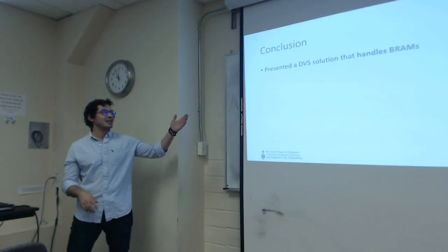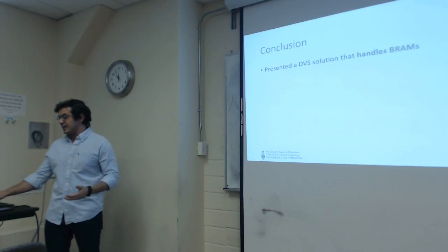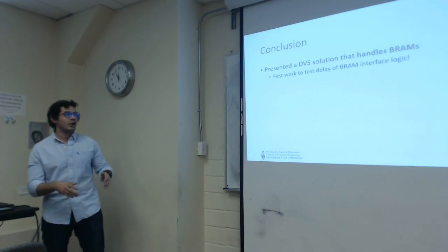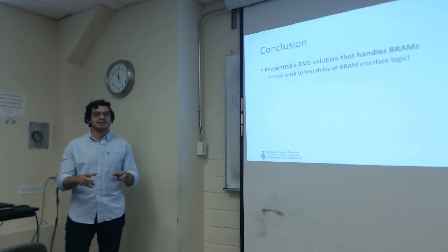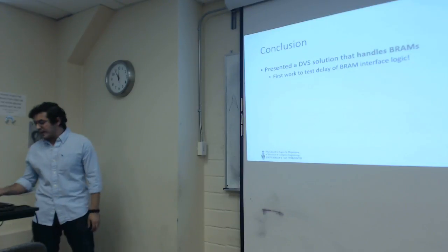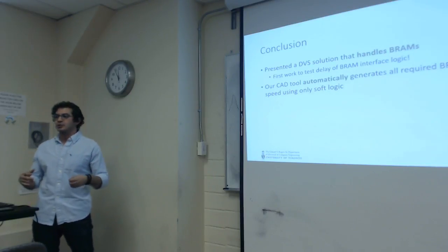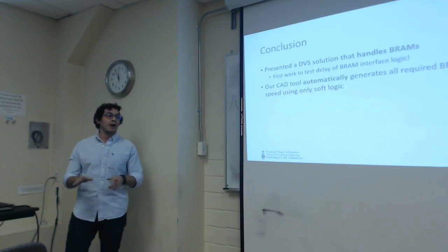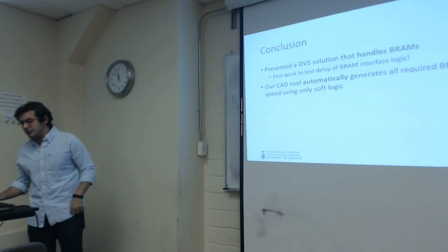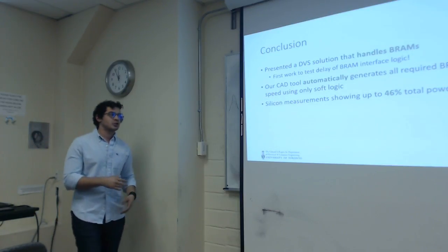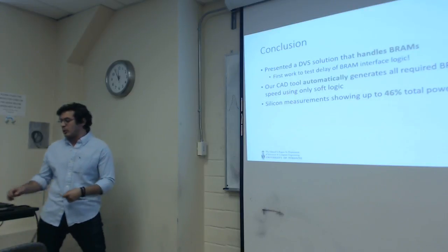And so finally my conclusion slide. In this talk, I basically presented the DVS solution that handles BRAMs. To the best of our knowledge, this is the first work that handles DVS using BRAMs. And our CAD tool automatically generates all these BRAM testers, so the user doesn't have to add any manual work from his or her side. And our silicon measurements showed up to 46% total power reduction.